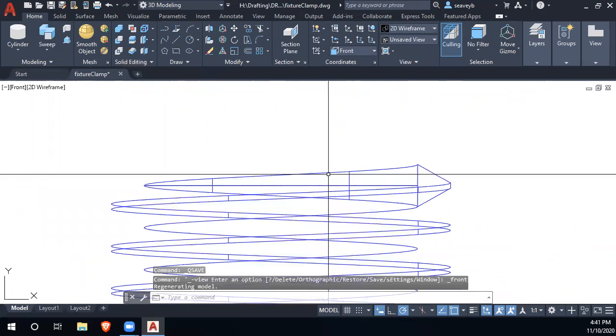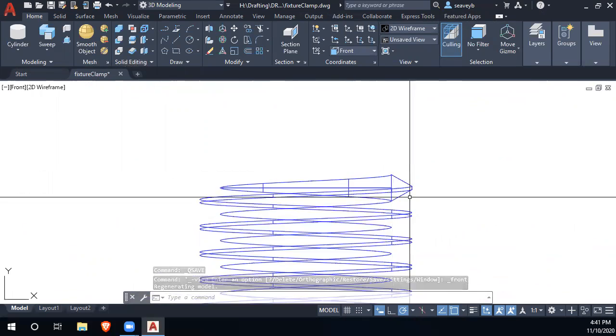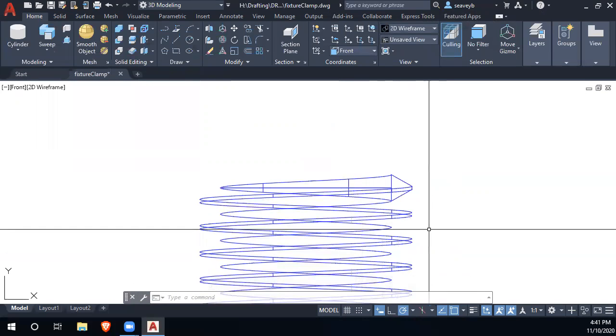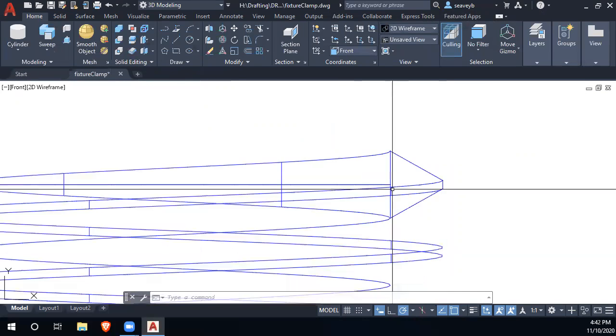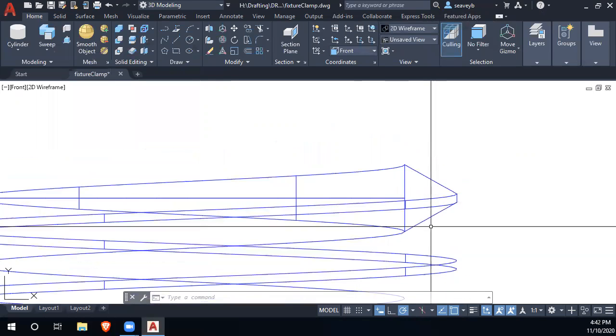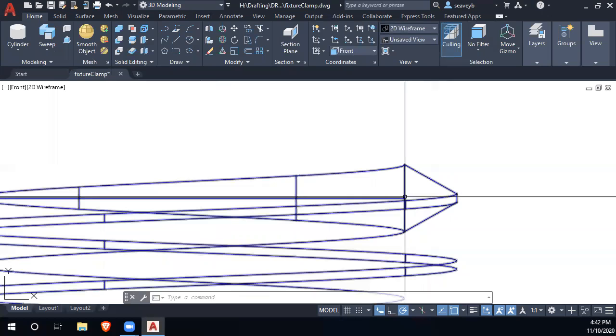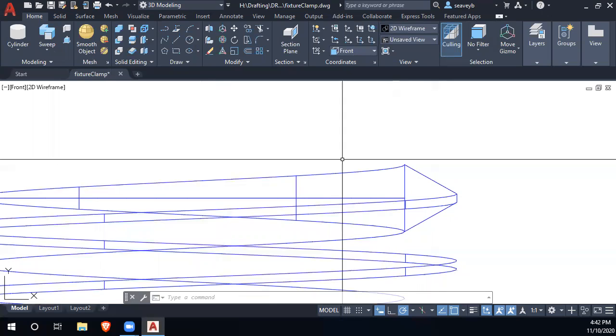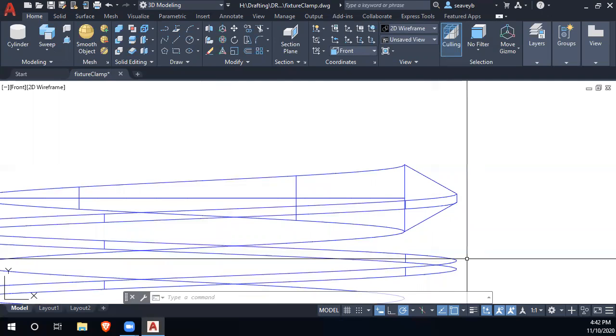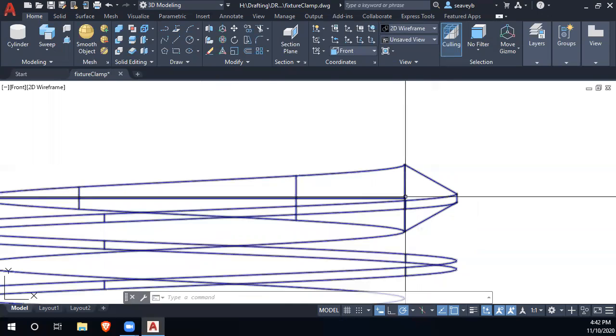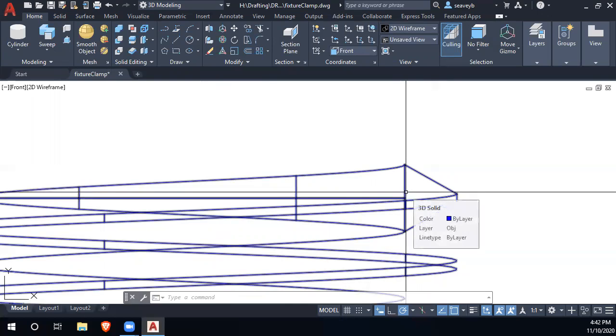Since the chamfer tool is not going to work, we have to build our own chamfer. A 45-degree angle chamfer on this thing ought to work okay. And I still see this edge right here. So I'm going to use this edge to build the chamfer. So, I'm going to draw a line.